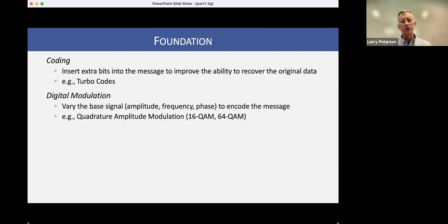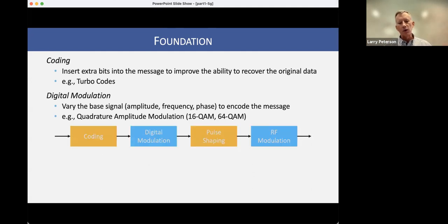So at that point, with that little bit of understanding, yes, there's coding. Yes, there's modulation. The modulation that gets used is basically 16 QAM or 64 QAM, which the way I think of that is there's either 4-bit symbols or 6-bit symbols that I can transmit in any time unit. And yes, certainly I code the data, I put some redundancy into it, and I modulate it to get so many bits transmitted per time unit.